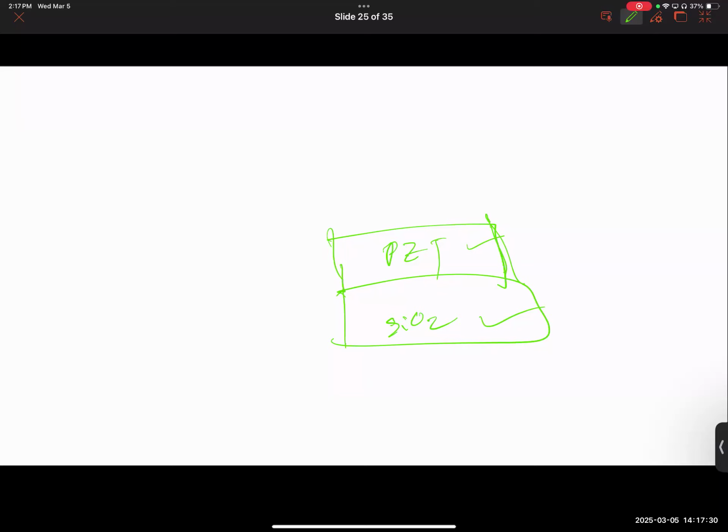Okay. But what if I told you that you have hafnium oxide that you already use? All I have to do is, when we fabricate hafnium oxide, I'll have to dope it with zirconium oxide. So this is a doping. You guys must have heard about doping, right? P-type doping, N-type doping, right? So basically, when you introduce an impurity in a material, that's doping. So hafnium oxide was pure. You're introducing some additional random oxide called zirconium oxide there. And what you get is HZO, hafnium zirconium oxide. And that becomes a ferroelectric. And so people discovered a technique to make hafnium oxide ferroelectric.